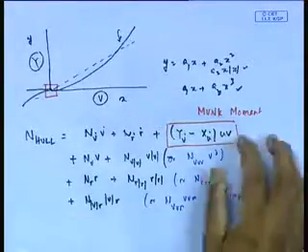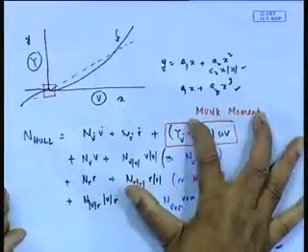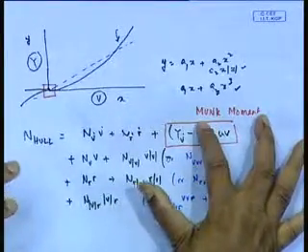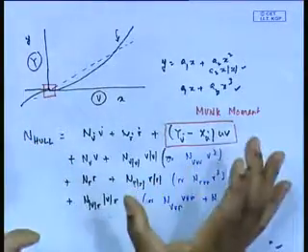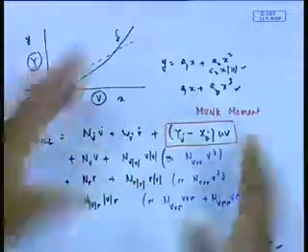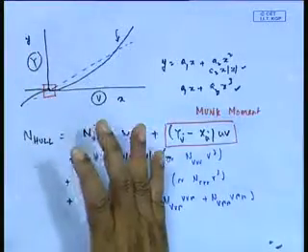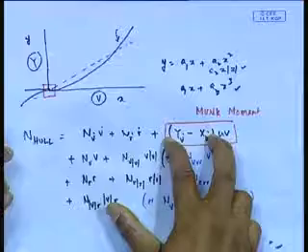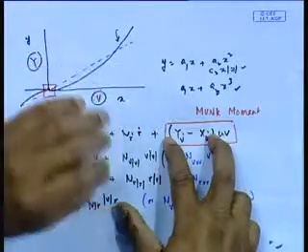And I can tell you one interesting thing: whenever people take the dynamics of aircraft structures and missiles, for example, and try to use that for marine bodies, they never understand that added mass forces are important, because in aircraft added mass forces are very small, since the acceleration of fluid forces is extremely small.